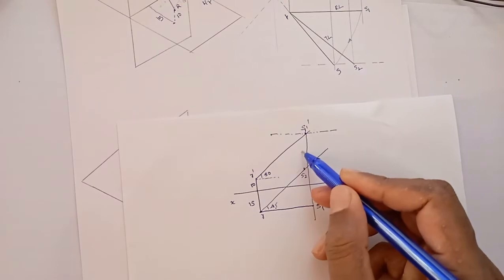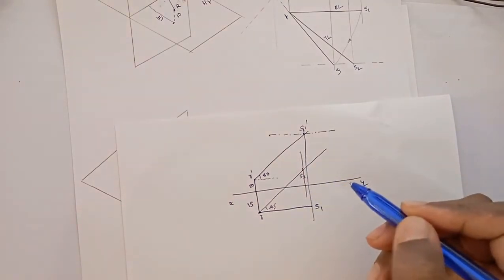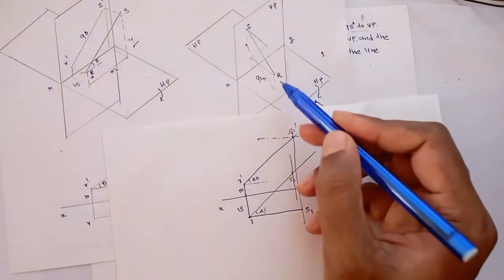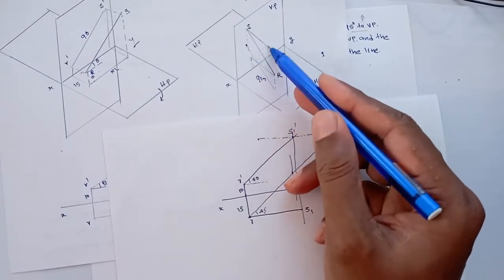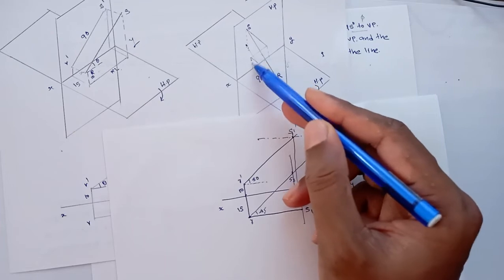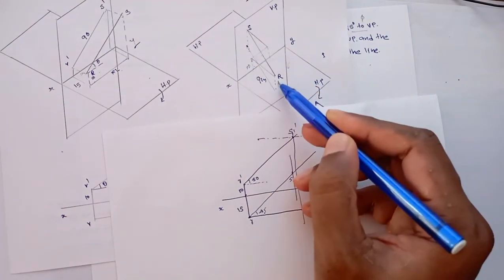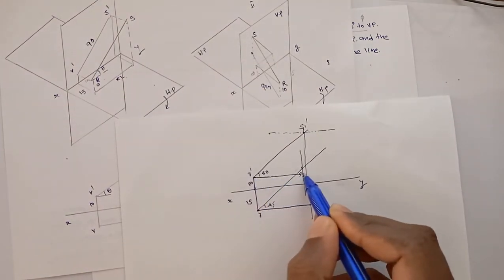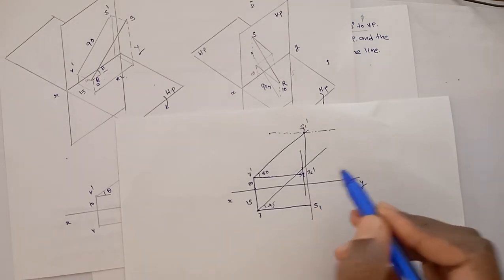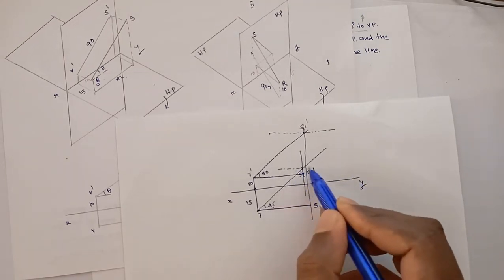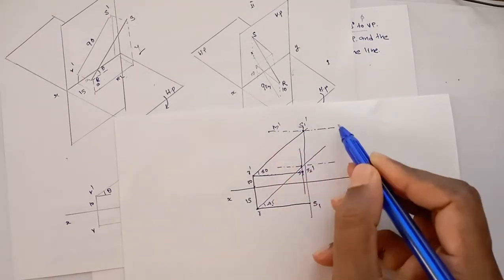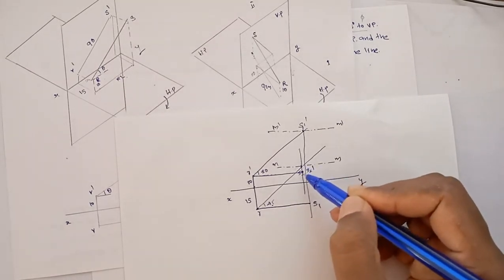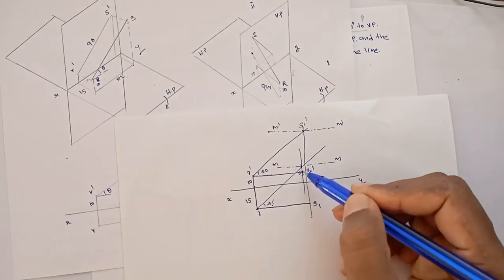And here you need to draw the projection line. This is our projection line, and its front view. What about the front view? Front view will be a straight line parallel to XY line. Above, what about this distance? This is 10 mm, right? Because this is also 10 mm. So we will get a front view here. This is our S2 dash. Okay, so this is our locus point. This is M dash, this is M. Because the front view and top view will be above XY line. Okay, because this point S is in second quadrant.